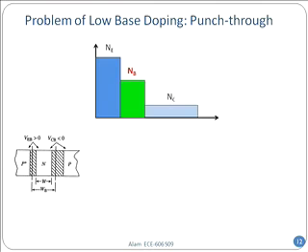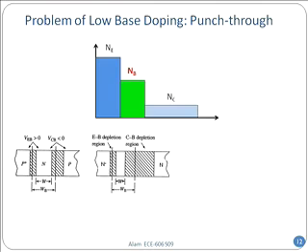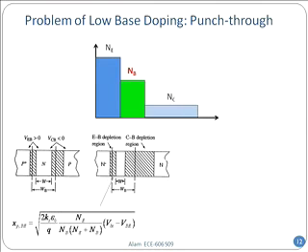But do you see this WB, what was my original base? That width of the green region. That is not really the base because of this depletion. Because of this depletion in the base emitter junction, we have done this formula before, right? The amount of this depletion region because of VBE for the bias, whatever region I have.